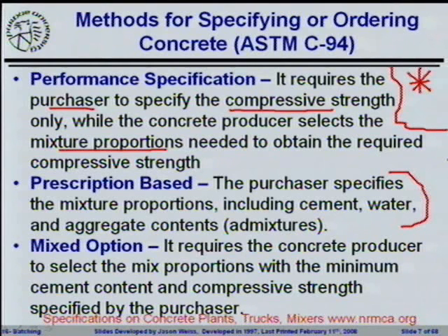And they're going to say, give me 564 pounds of cement, give me a water to cement ratio of 0.42, give me 1,200 pounds of aggregate, and I want that concrete. Now there's a big difference here, because they are giving you the recipe, and in theory, you are just mixing their materials together and delivering it to them. They are assuring the performance is going to be obtained. They should be making any sort of changes on site to this.